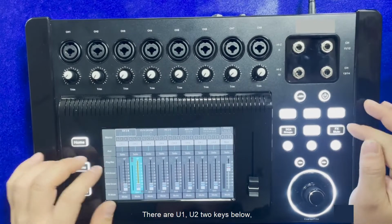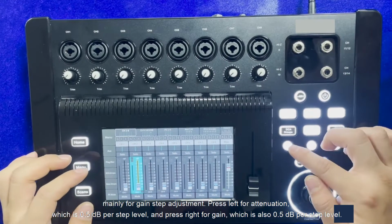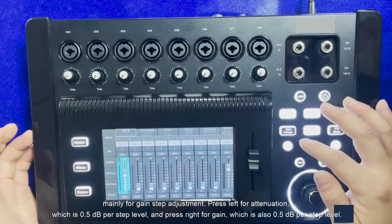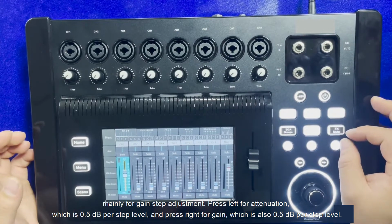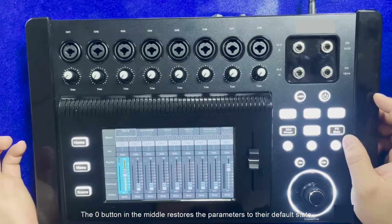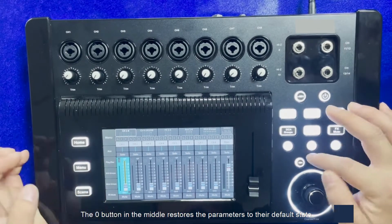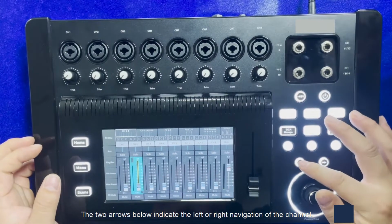There are U1, U2 keys below, mainly for gain step adjustment. Press left for attenuation, which is 0.5 dB per step level, and press right for gain, which is also 0.5 dB per step level. The 0 button in the middle restores the parameters to their default state. The 2 arrows below indicate the left or right navigation of the channel.